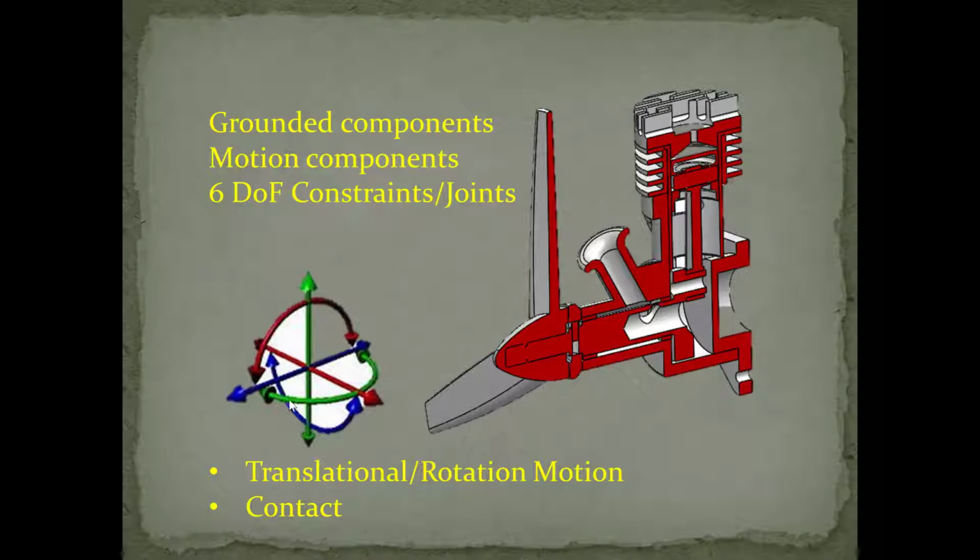It can rotate around Y, it can translate on Y. It can rotate around X, it can translate on X. Or move in a straight line, it can translate on Z, rotate around Z. So our job is to remove the excess degrees of freedom till we have the mechanism operating with the proper motion. And then we join together the various joints to get the mechanism motion that we are after.